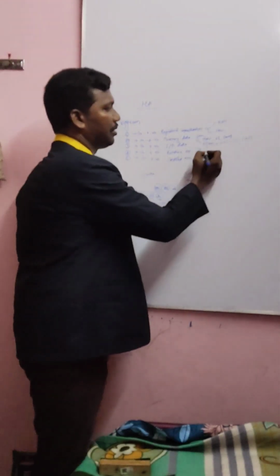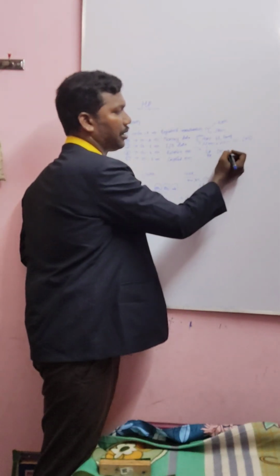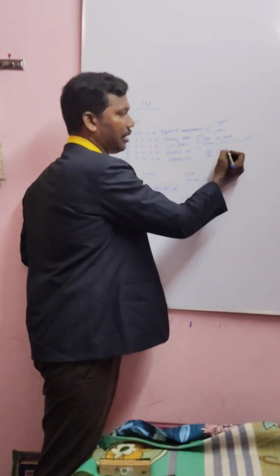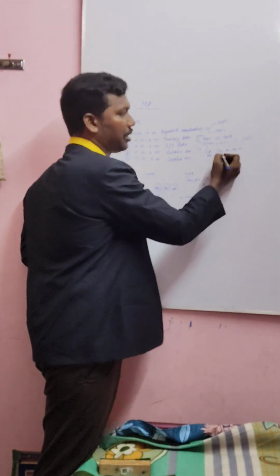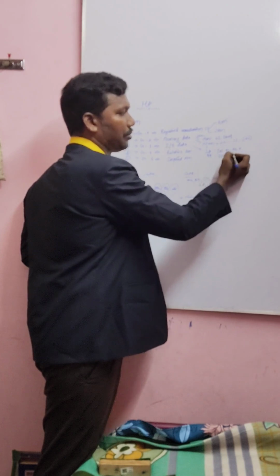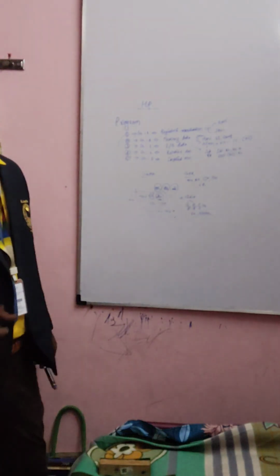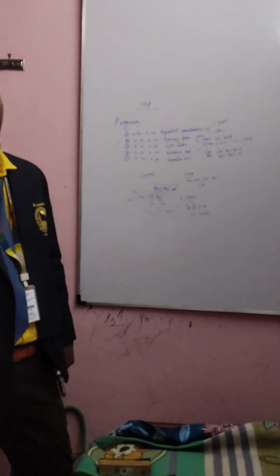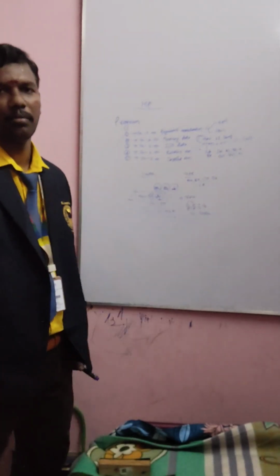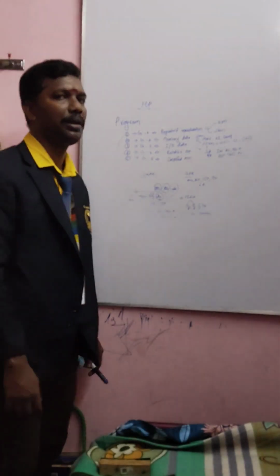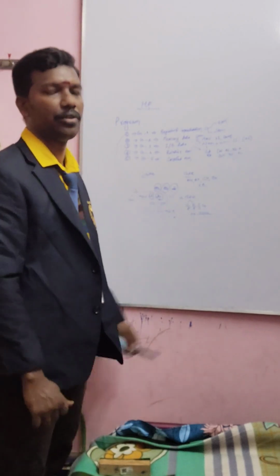So how are we going to represent that? Input or output. For example, IN AL, 02H, or OUT 02H, AL, anything can be used. It means the AL accumulator points to the address, not the data. With OUT, it is not necessary to put a square bracket; only for the direct form can we use it. Otherwise it will be understandable. If you want to remove it, no problem at all. This is the correct one as per the mnemonics, so you can use it.